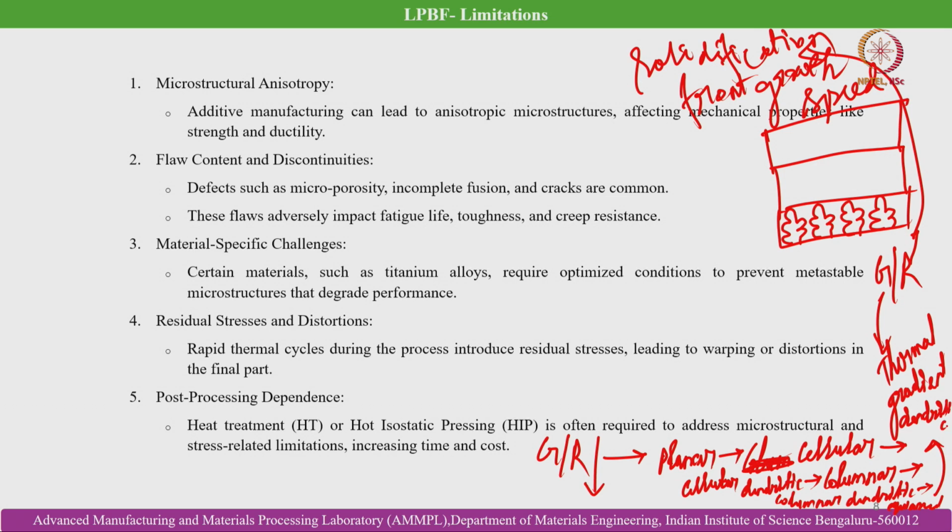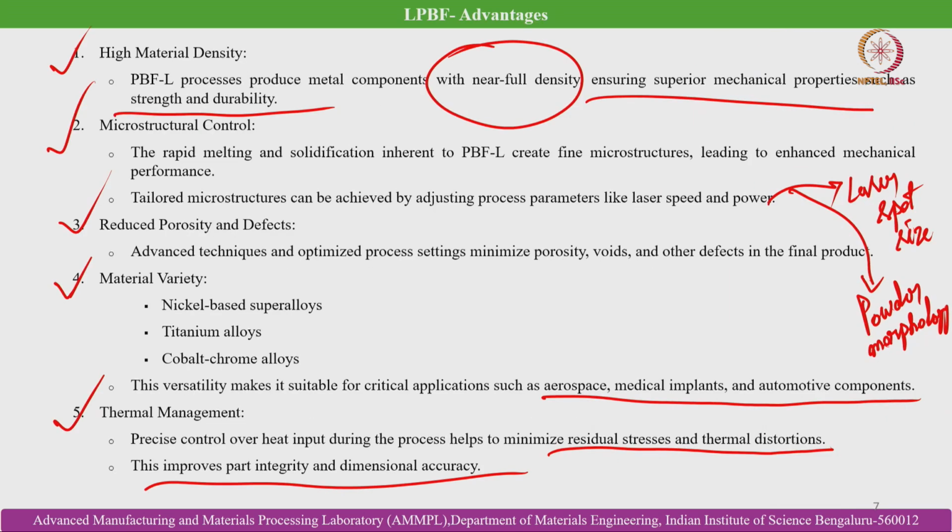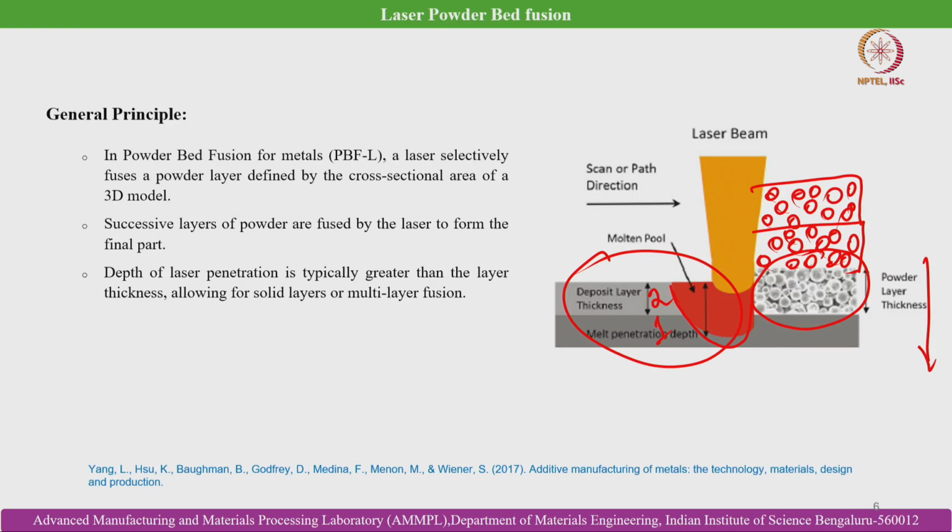It also happens in other kinds of laser based additive manufacturing processes, and also arc based processes. So, that we will discuss later. Let us focus our attention on LPBF now. So, you can see that based on the local thermal gradient and cooling rate conditions and solidification front growth velocity, the microstructure changes. So, then you can see different microstructures in different layers, and there is another aspect which demands attention, the direction of the heat flow. Because we are talking about an elliptical melt pool like we discussed in the previous slide. So, you can see this is an elliptical melt pool.